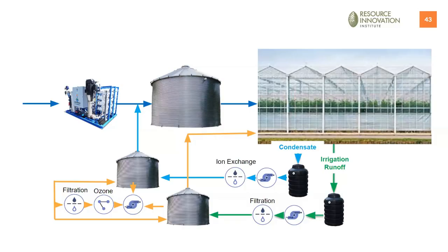Now, down at the left-hand side, this is a schematic for an ozone filtration system. And we'll just recirculate the waters from both the dirty water tank and the clean water tank through this ozone generator. And that'll distribute ozone into those tanks and maintain an ORP level, an ozone concentration, to keep those tanks disinfected so that high levels of bacteria and pathogens don't build up in those tanks.